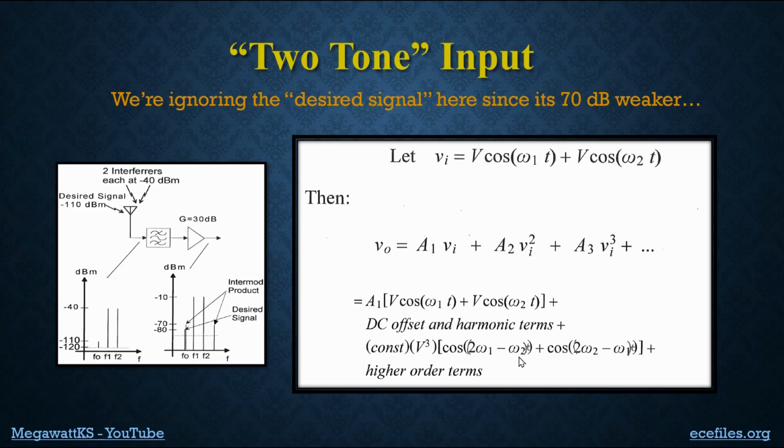What about the frequencies here? Well, the first one is the intermod product that flanks on the left. And it's separated from the two signals that created it by the distance between those two signals. So that's what I'm trying to draw here. This term, 2 omega 2 minus omega 1, we take the frequency f2, or omega 2, and double it, and then subtract off f1, so we don't come back fully, we only come back to here, and that's what creates the right-hand term.